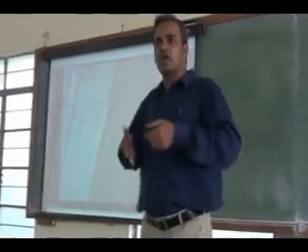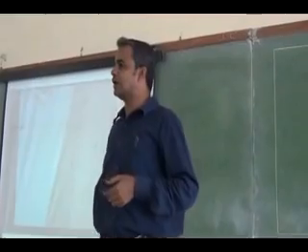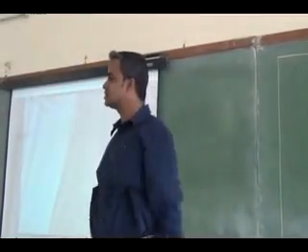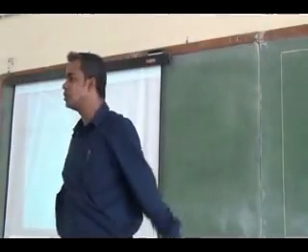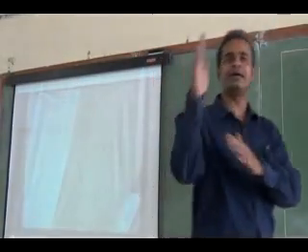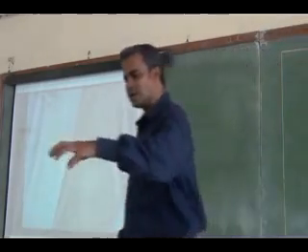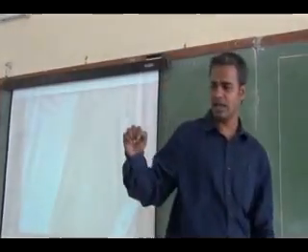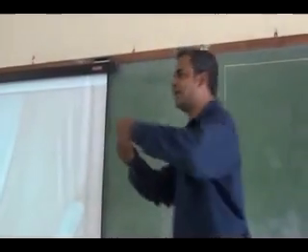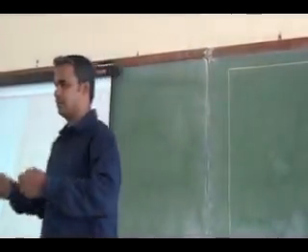So fix the drafter rigidly to the table. With my horizontal scale I can draw a vertical, perpendicular line. I can draw parallel lines to any line, and any inclined line. I have protractor graduations in the middle. Over that blue plate I have a marking that defines the angular orientation.